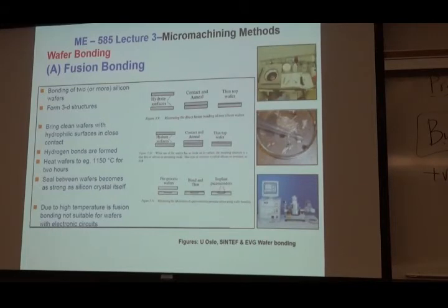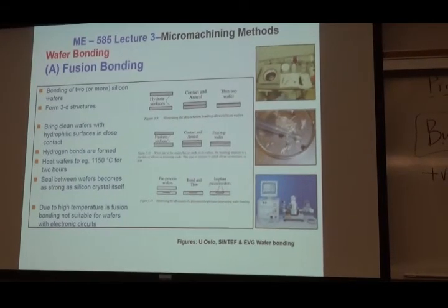Again, the story I forgot to tell you: the reason you don't want HF is, first of all, it's gas. It's all over your facility. You can't control it if some valve is not working. When I was involved in the design of the EIS building, we had to design some of the piping. We have four types of pipes, ducting, and some of them are just for HF.